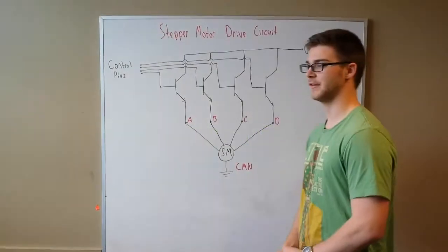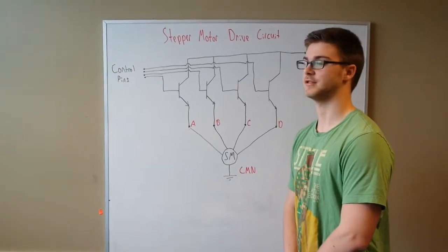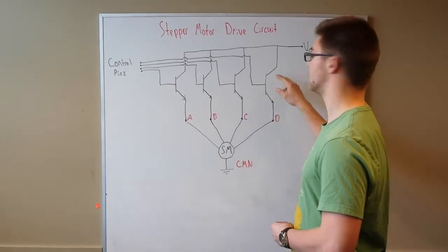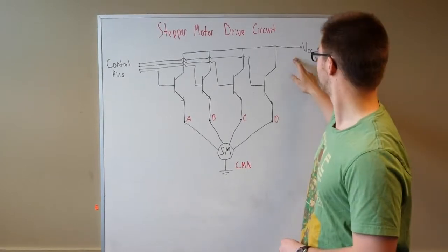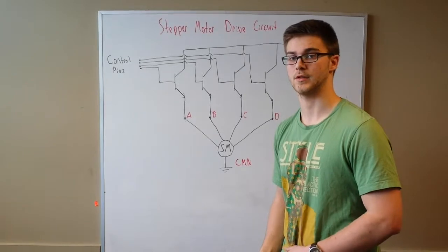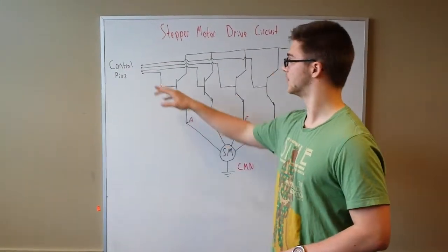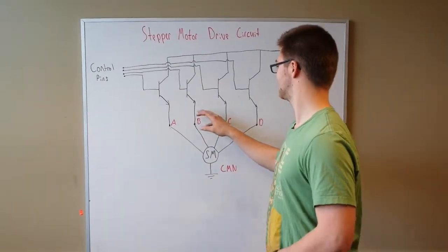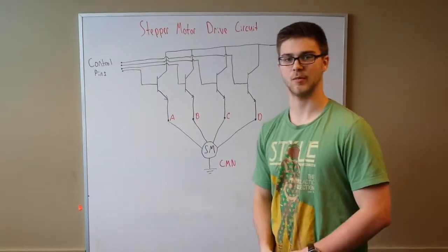This is the stepper motor drive circuit we used to control the stepper motor, which was rotating the light sensor I mentioned earlier. It's composed of 4 NPN transistors, the collector pin of each of which was connected to a supply voltage. We use voltages between 3.3 volts from the TIVA board all the way up to 10 to 15 volts from a benchtop power supply. The base of each transistor was connected up to control pins leading to the TIVA C board. The emitter of each transistor was connected to the wires that come off of the uniphase stepper motor.